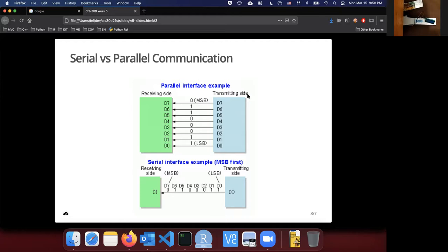Synchronous means there is a clock that synchronizes the data sending transactions. Basically you have a pulse, and upon each pulse, you send some data over, or the data is read. So there's timing of the signal: when you send a signal and when it is sampled or read is precisely timed. So it's on a clock.